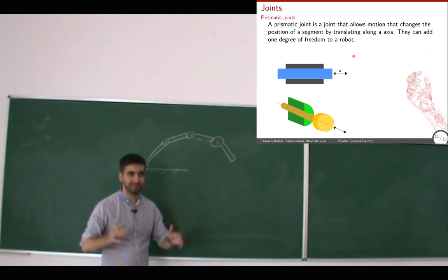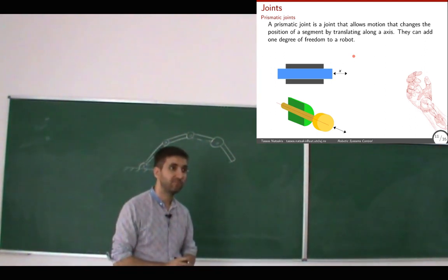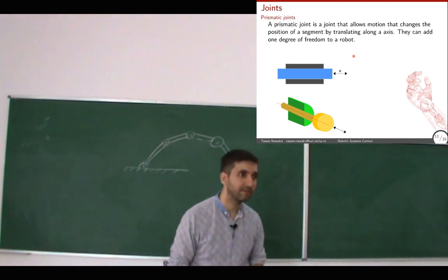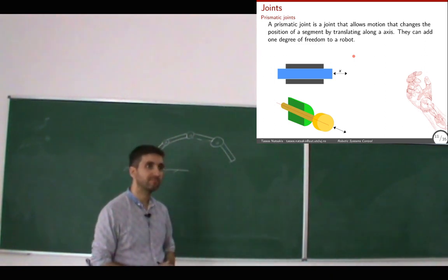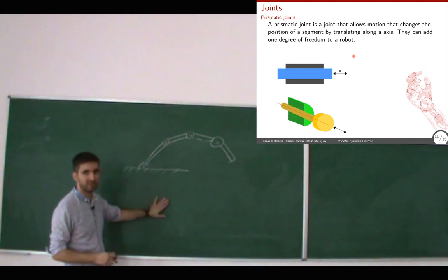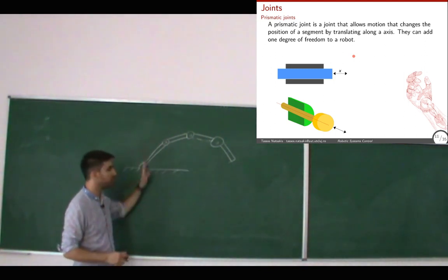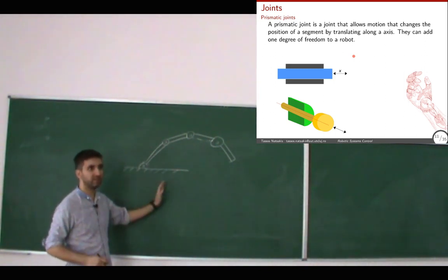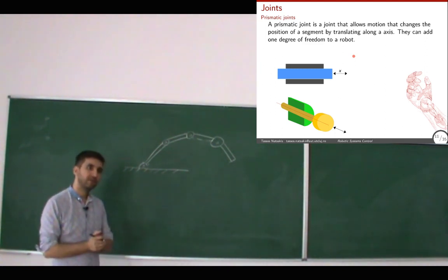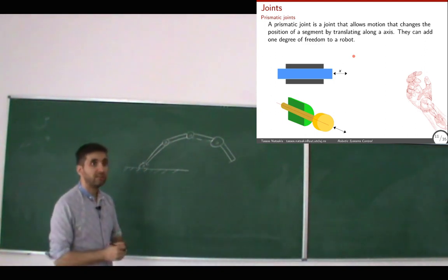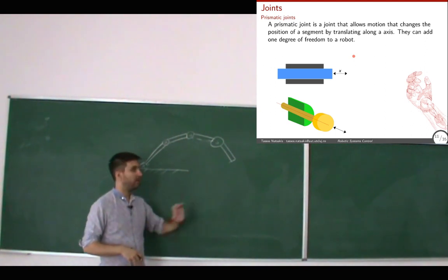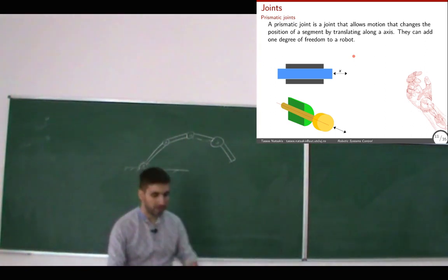There is none. We did not have any other coordinate. So basically, it's these 3 things that I can change on this surface here. I can change the position in 2 directions independently, and I can change the orientation, but there's nothing else I can change. We added a new way to reach a certain state. Yes, we added more flexibility. So now the robot is even more capable of reaching any position and any orientation.